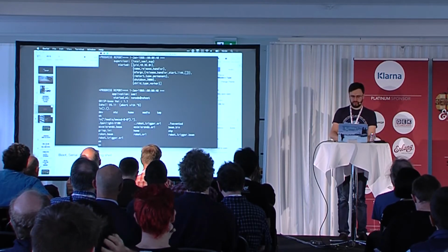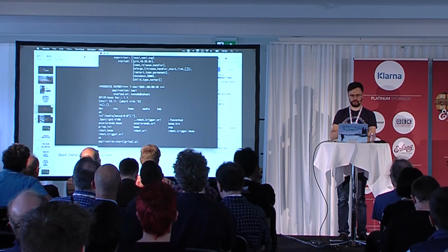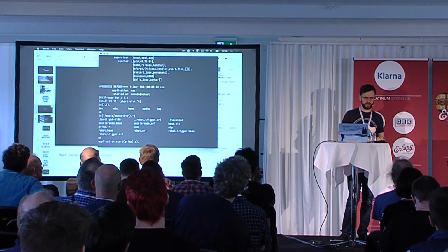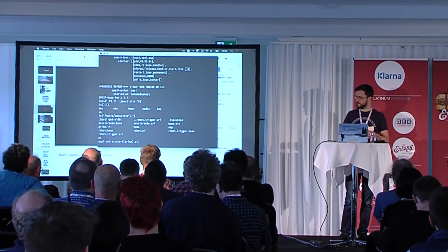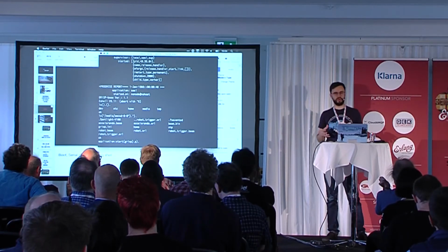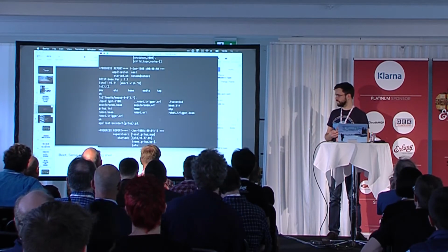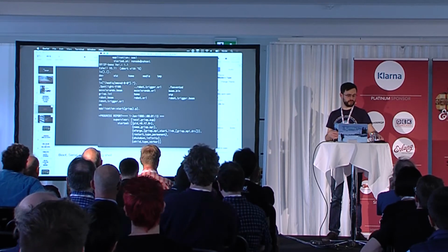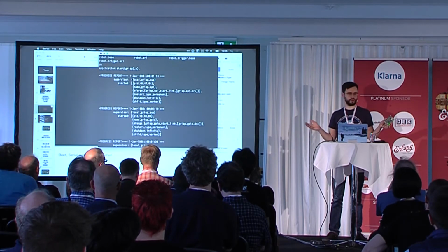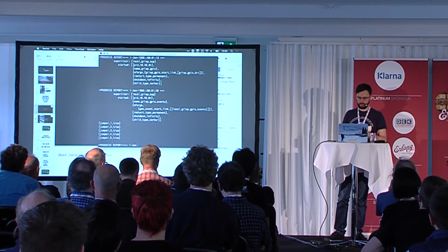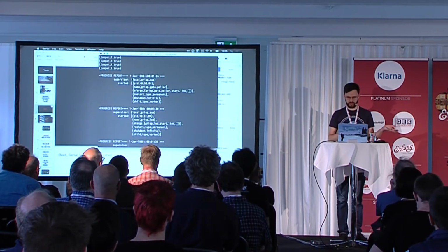And to spice things up a bit, we have a GRiSP runtime. So I can do this. This will be a bit slow again because now Erlang goes down to the SD card and tries to search through the code path everywhere to find the right modules. So soon the SASL output will come. The GRiSP runtime is basically an Erlang application that runs in this Erlang VM, has a couple of processes and has a couple of drivers that can interface with the GRiSP hardware. So it provides you with a high-level Erlang API to all the nasty hardware stuff. And it's starting to become quite a few processes because we have some different ports and functionalities.